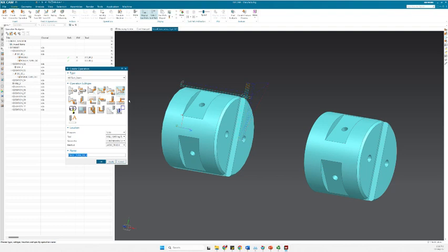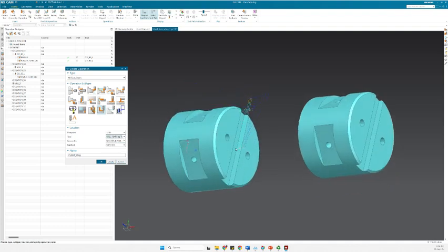And for the operation, I will select floor and wall, which depends on what we are defining in the milling machine. Floor and wall in the same program, and the tool we're gonna use, let's say, is the end mill number 1 that we used. We're now gonna aim to machine this part. For this one, we select the machine coordinate system on the mill. And most importantly, don't forget to define this correctly. So we will, for example, use mill finish polar. So we're gonna reach the final geometry in the same machining operation.